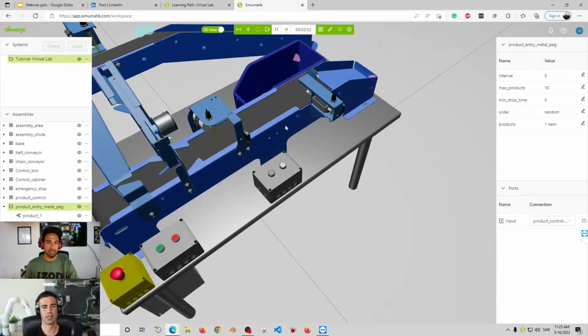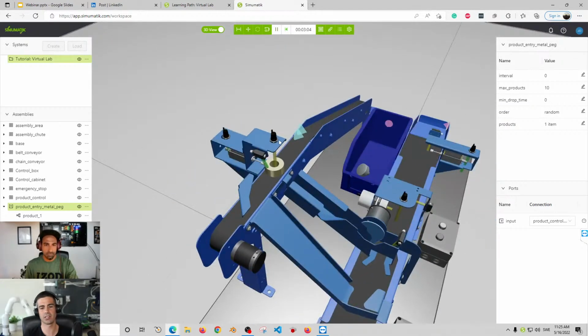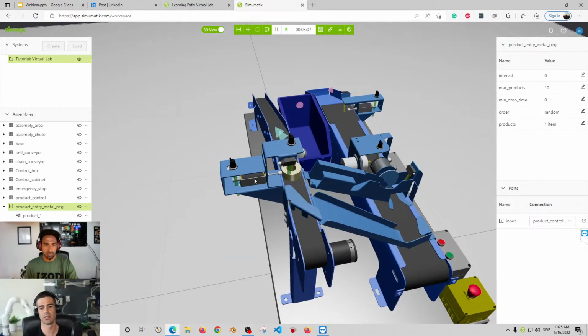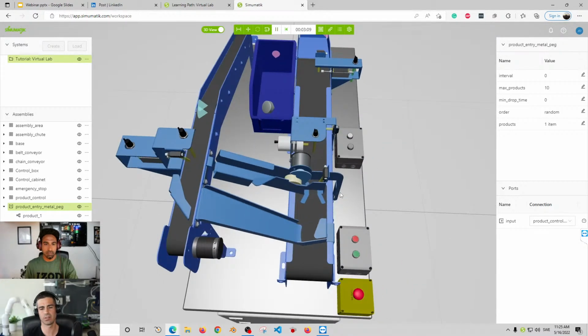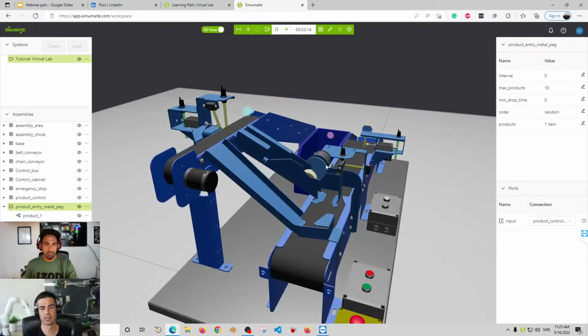Let's have the second piece, which is the plastic ring. Again, in this case, the idea is that when the plastic ring comes here, it's not detected by this sensor, just by this one, and then we can push it, and it's going to fall down here. Here we can build a buffer of rings. And when we click on this, we just release the part, let one pass. Now we can bring the lower part. Now we can bring the second part.